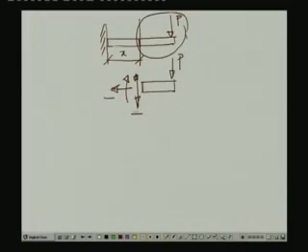Now, depending on the type of loading or the forces that the beam member will be subjected to, we will have these quantities. Here, since we do not have any horizontal force component acting on this beam, clearly the horizontal reactive force will be 0. When we get this vertical internal force, or stress resultant, we call this vertical stress resultant the shearing force V.